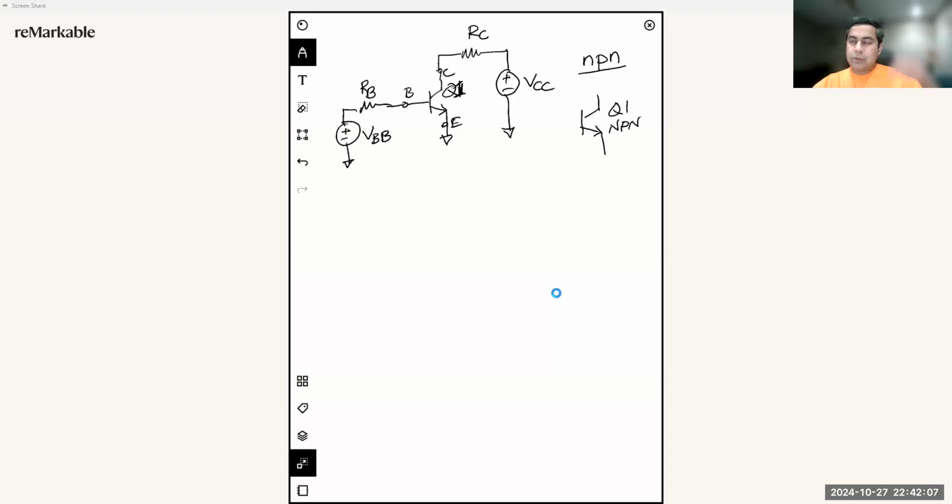But what we are going to do is select the model number. Previously, you opened the component attribute window and edited that while you placed a model file in your LTspice directory. But here we can pretty much use the devices that we have in the library. There is a library of BJTs that LTspice already contains. So we are going to use one of those models to simulate our devices. The model we are going to use is numbered 2N3904.